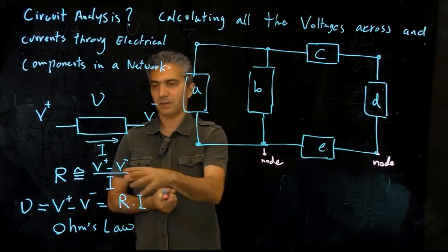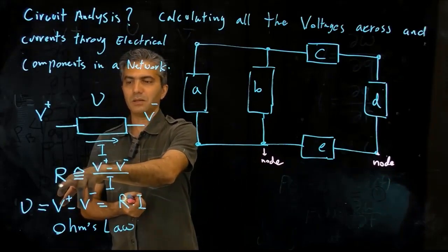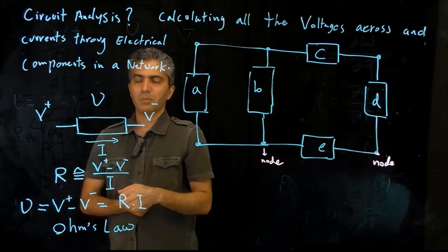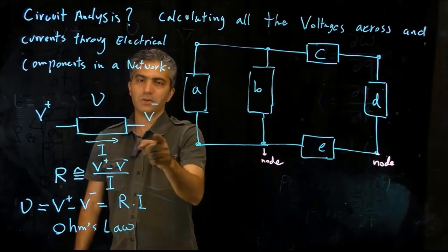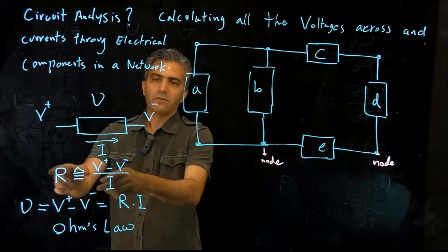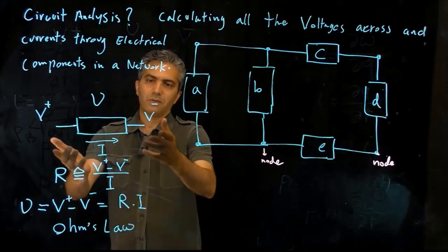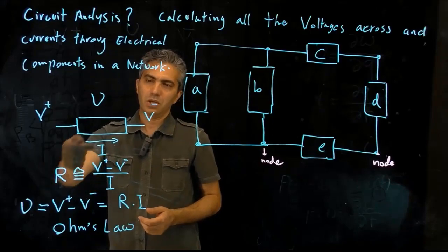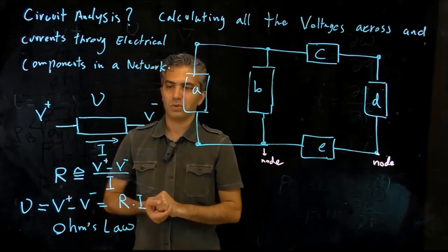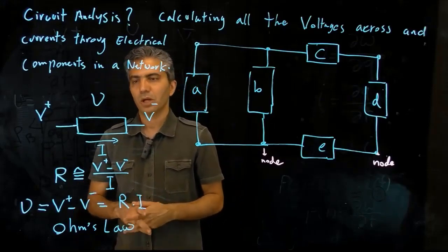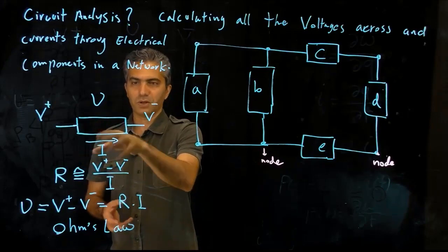Okay, so now this resistance, this quantity, has a really valuable application, because now I can compare materials in terms of their resistance against passage of current. In other words, this value quantifies how much current I get for the same unit voltage applied across the material. If you are looking for more current passing through, then you need to reduce the resistance. If you're looking for lower current to pass through, then you have to increase the resistance of the material by choosing a different kind of material or a different geometry, because this resistance is both a function of the material property and a function of the geometry.